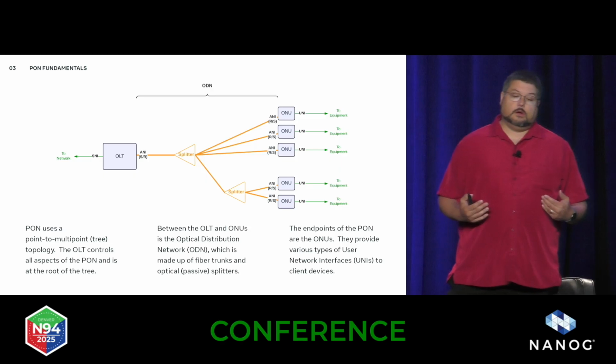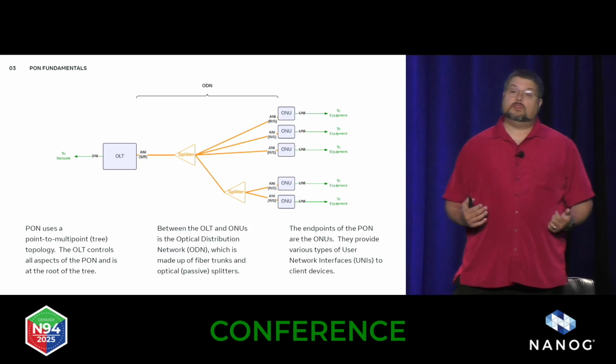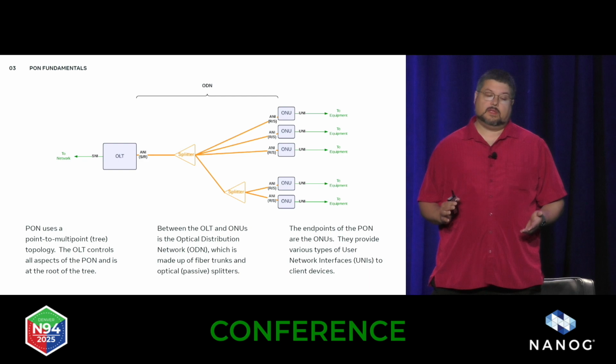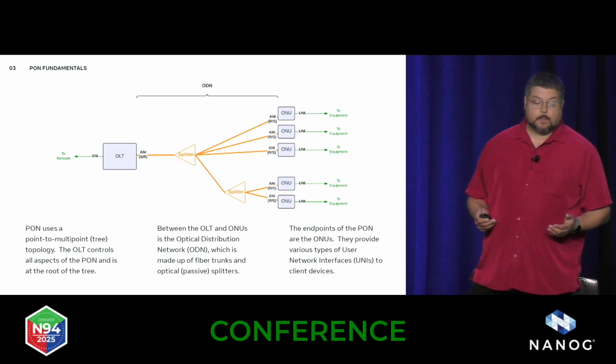Both the PON OLT and ONU lasers have a fairly high output level, and the receivers are quite high sensitivity. So that gives us quite a large power budget between what we can afford to burn, both in terms of fiber distance, splices, and especially the split ratios that we handle.